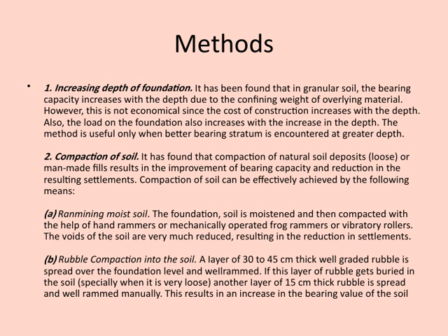However, while this method can be effective, it's not always economical because deeper foundations mean higher construction costs. Plus, as you go deeper, the load on the foundation also increases. So, this approach is most useful when you encounter a better, more stable soil layer at greater depths. Next, let's talk about soil compaction.